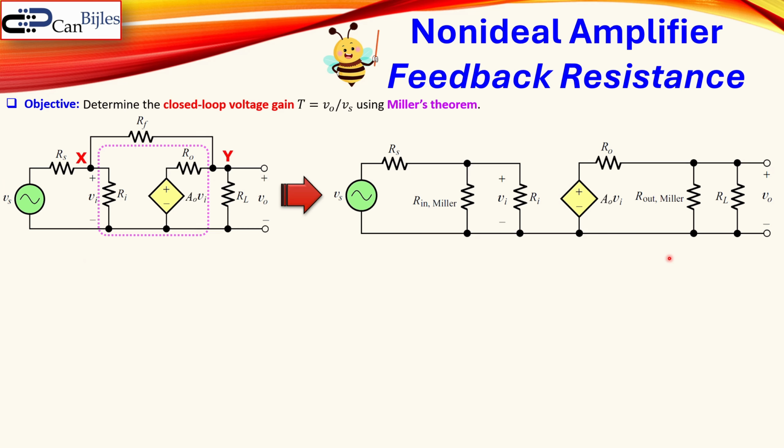First we designate the nodes X and Y here and also the same nodes there. We start by defining our open feedback voltage gain. What does it mean by open feedback voltage gain? Well, we break the feedback loop, so this will be an open network. And that will then be the voltage gain, which I call AXY, from this node to that node.